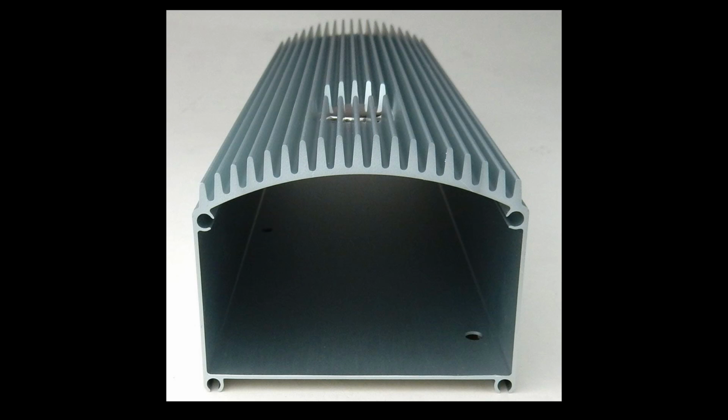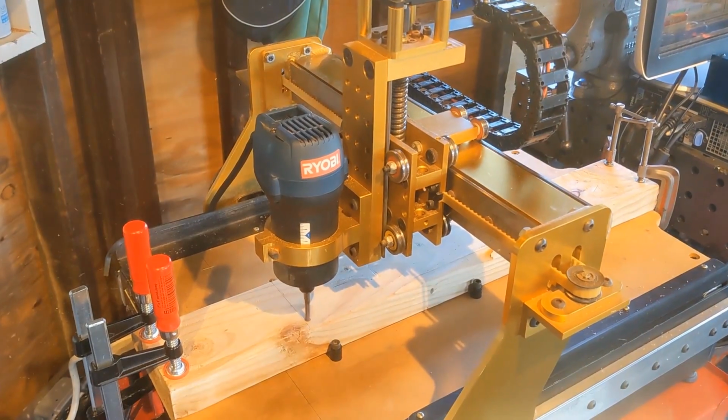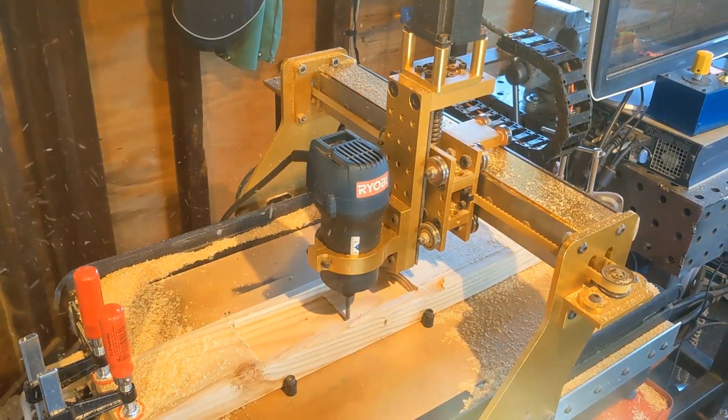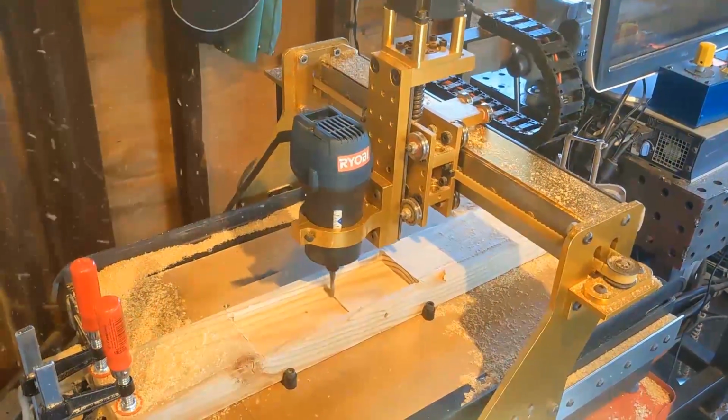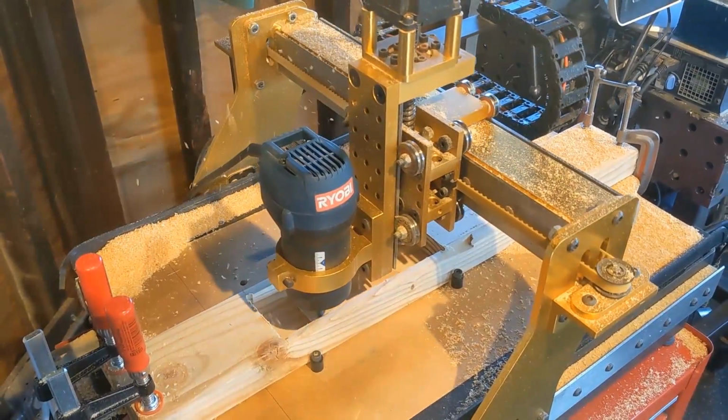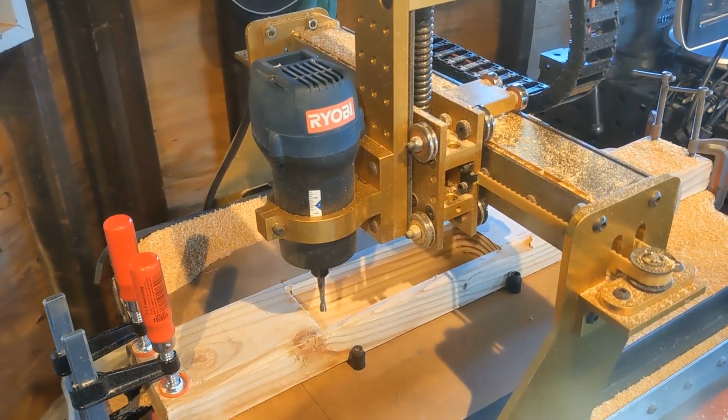I need to make some cuts in the aluminum case to mount the LCD display. The aluminum case has a concave back, which is hard to clamp down on the bench, so I cut a pocket in a scrap 2x4 with my Romex HS1 to hold it securely. I designed the holding jig along with the other holes and cuts in VCarve Pro, so no measurements are necessary. Just drop it in and cut.